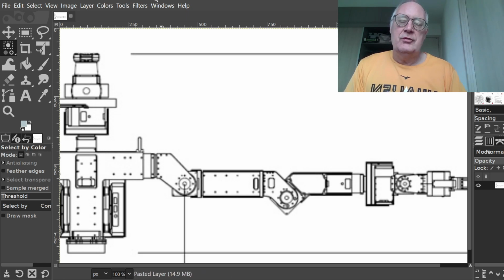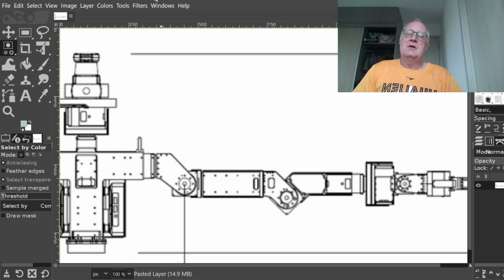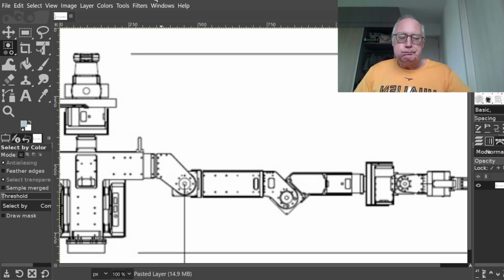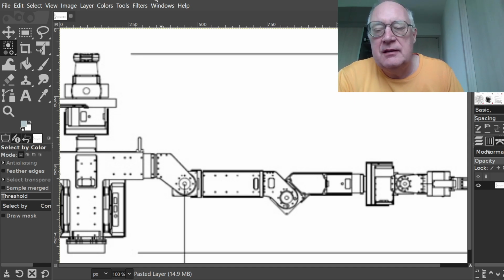So now you can also do a screenshot and then draw in the z-axis that you want to assign. Probably easiest if you start with the joints first, assign the z-axis for the joints, and after that assign the z-axis for the inertial frame. And that is the same way that we did it previous class as well.